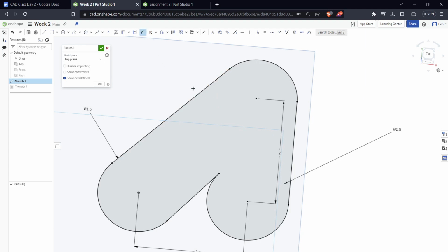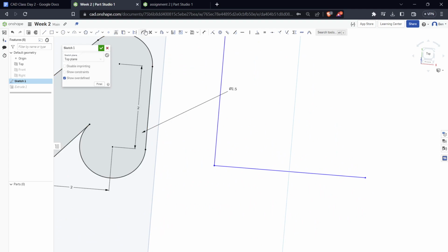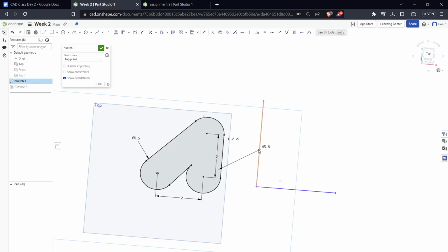Sketch fillets and three-dimensional fillets, they're the same principle, where you're taking a hard angle. So let's say I have a 90-degree angle like this, and I'm making a fillet. I'm pretty much filling the area to make it smooth. So if I click these two lines with the fillet tool, it will let me round out that hard corner. And that's quite useful because you don't want a lot of sharp edges, because first of all, they build up a lot of stress.